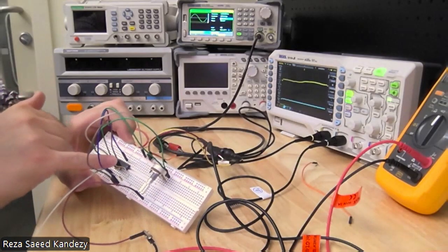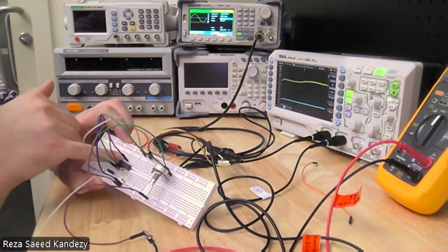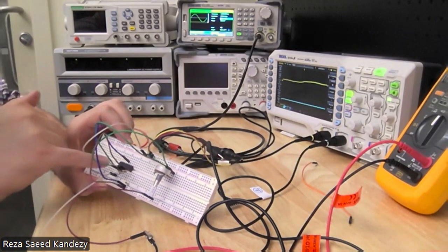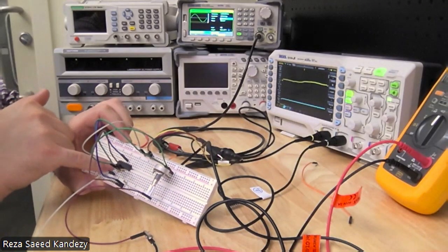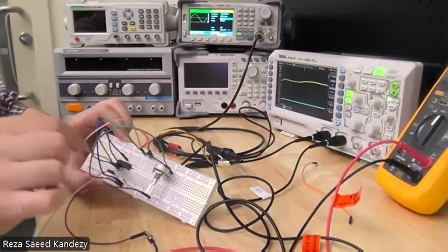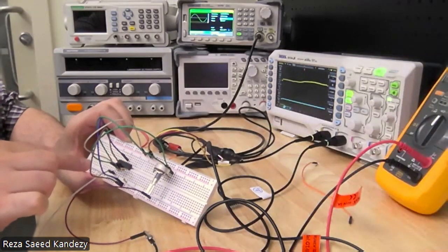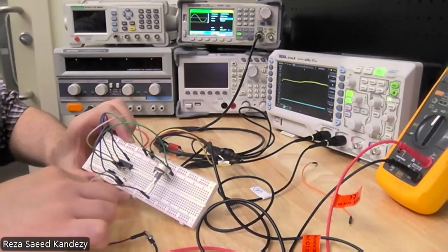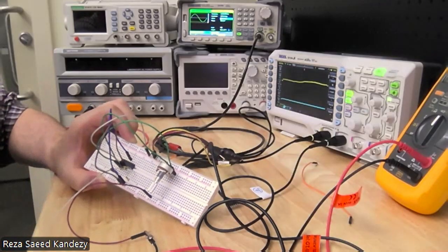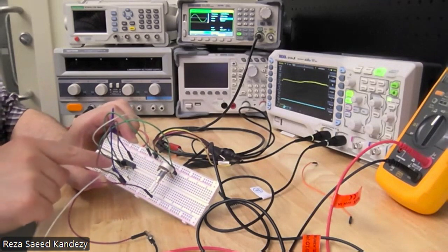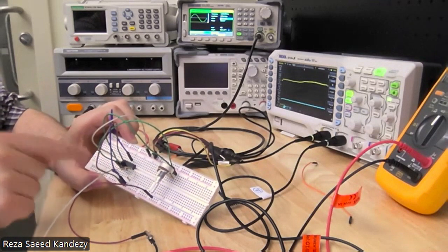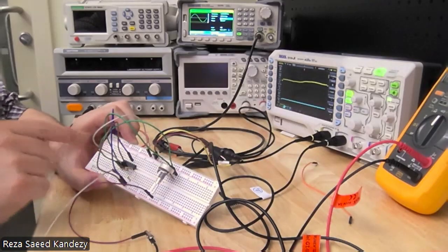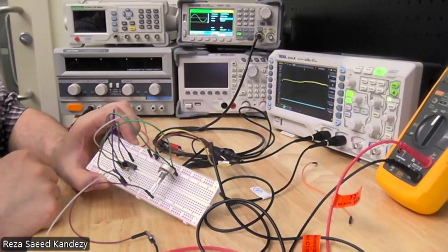I connected the 4th pin to the VCC and the 11th one to the ground. Now I'm going to use the non-inverting pin, which is the 3rd pin, as an input. It's connected to the input. And I'm going to have the inverting one connected to the ground through that 170 ohm that we talked about. I am going to feedback the output, which is the 1st pin, using a potentiometer to the inverting terminal.